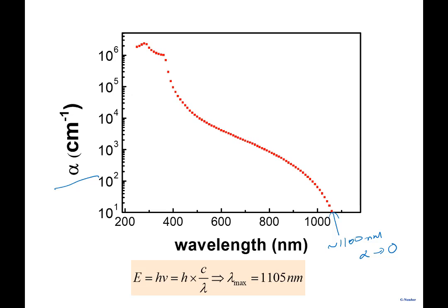After that, note that the characteristic of alpha is not simplistic. A simplistic understanding would have been, let's say, with energy of the photon, this is Eg, that's 0, then it goes up like this. It's not simplistic like this, that above Eg it will absorb all the photons and all photons are identical. Note that the absorption coefficient is varying with the wavelength here, right?